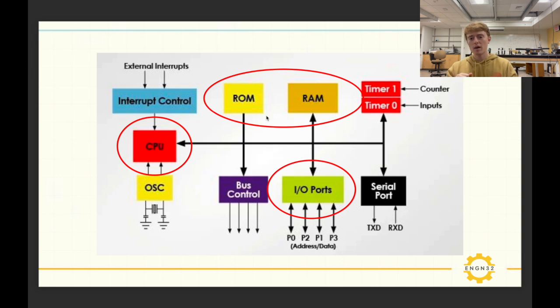So now the cool thing about having an electronically erasable ROM is that you can send code to your Arduino and then unplug it from your computer and go just supply power to it some other way, and we'll talk about how to supply power to an Arduino as we go forward. But that code remains on your Arduino in its ROM, okay? So it doesn't need your computer to run the code.